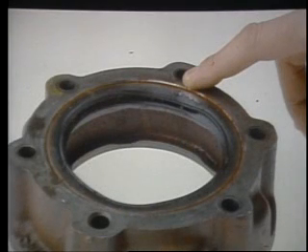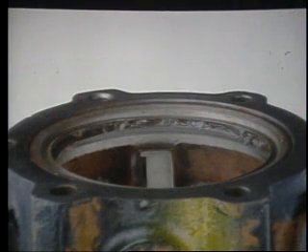Good seal performance is also dependent on correct installation procedures. No seal can be expected to do its job if it is not installed properly. When the seal is installed, it should not bottom against the counter bore in the rear bearing cover as shown here. This can crush the metal portion of the seal. When properly installed, the seal should be flush with the rear machined surface of the bearing cover.